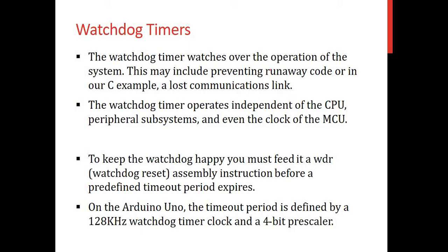Okay, so basically what we want is to prevent runaway code in the system. An important thing to note is the timer operates independent of the CPU, and it's also independent of the clock of the microcontroller unit.